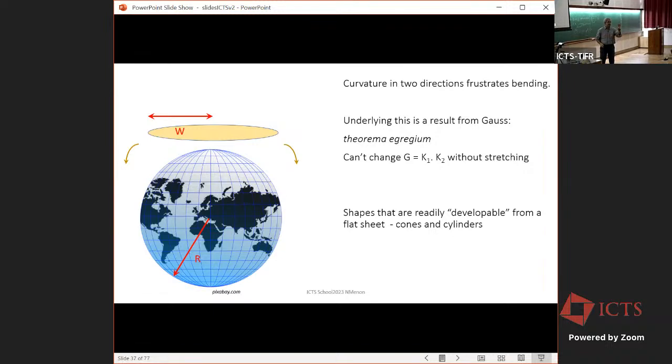You have a question? Go for it, and then you have a question over there. How did you get such a thin sheet? These thin sheets are made by a process called spin coating, which is a standard first step in photolithography. You take the polymer you want, mix it up in some volatile solvent, put it on a microscope slide or a quartz wafer, and spin it fast. All the solvent evaporates, and you're left with a thin layer of solid.